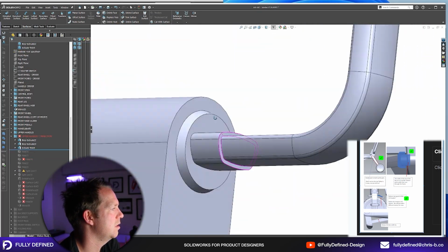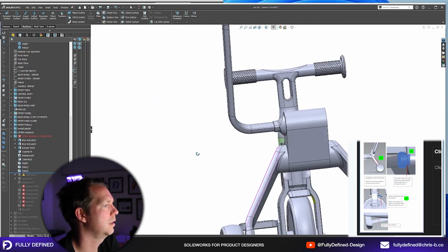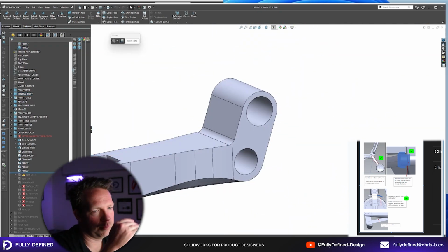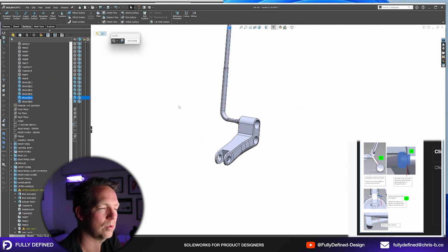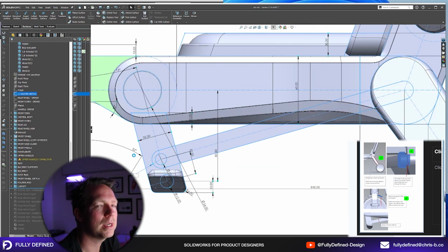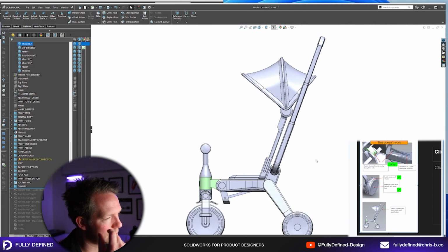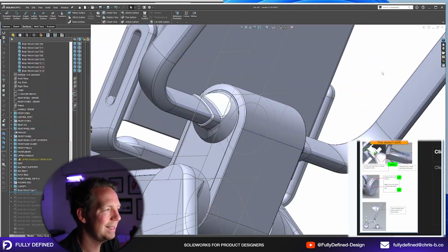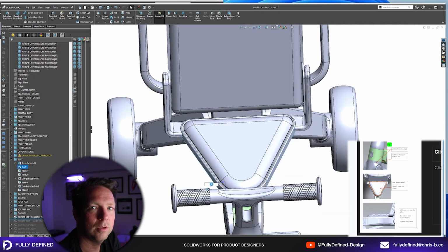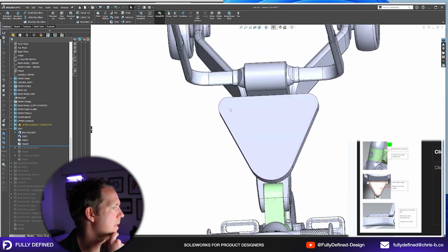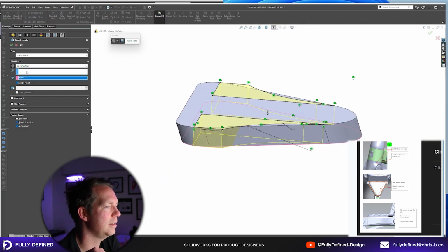So there's a constant process of refinement, making changes, moving up and down the feature tree, improving your modeling, so improving how something is created, making it more robust, meaning that as you make other changes to your master sketch, the features and geometry that you have made robustly don't fall in a heap when you make other adjustments to your model. And then rolling back down and clearing out obsolete features and cleaning up any dangling dimensions.